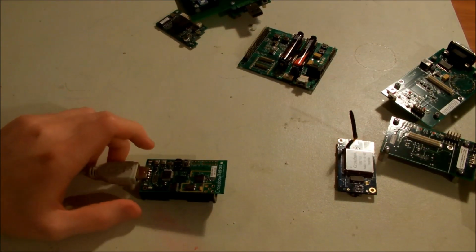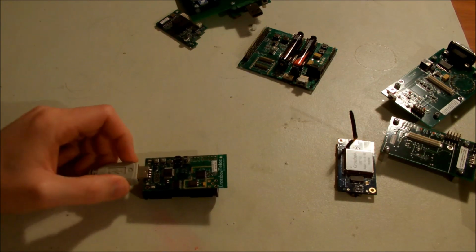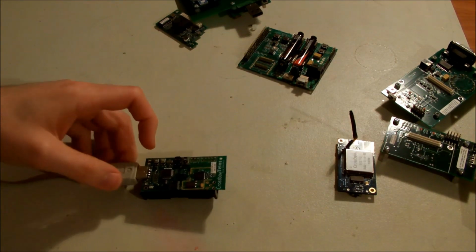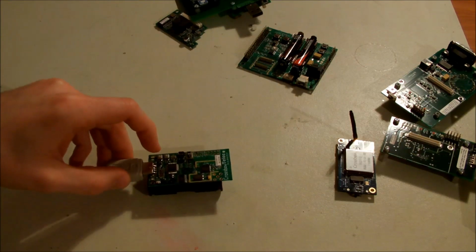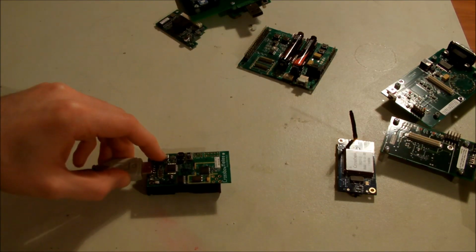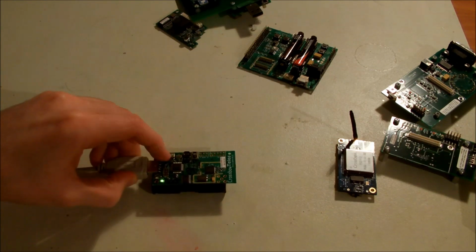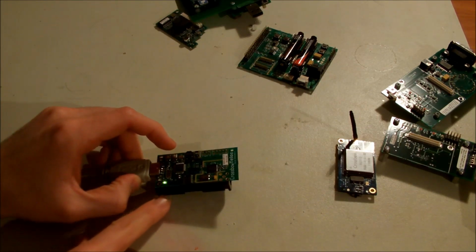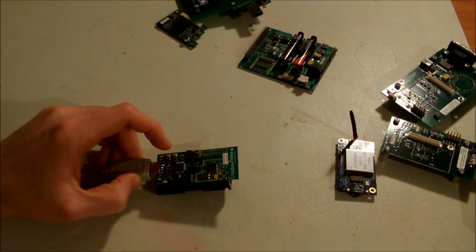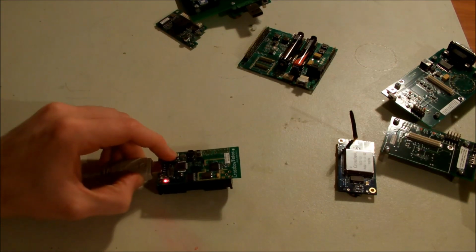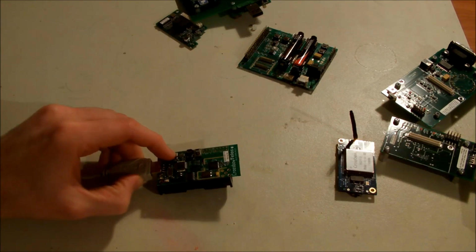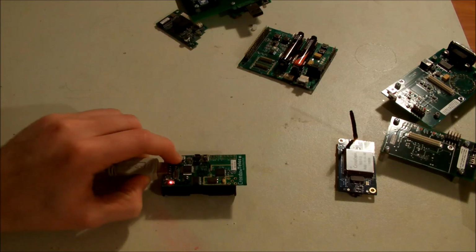So what we just did was adding a timer to our code to check if the button was pressed for more than 3 seconds. It will turn on the LED 1, or in this case the green LED of the board. So this is the normal one, pressing and releasing. After I pressed it for 3 seconds, it turns on. And if I don't press it after 3 seconds, it will turn off. You see, 3 seconds passed, it turns on, and 3 seconds passed again, it turns off.